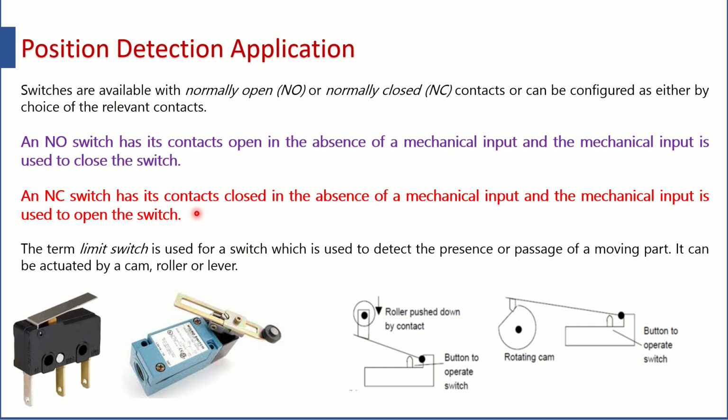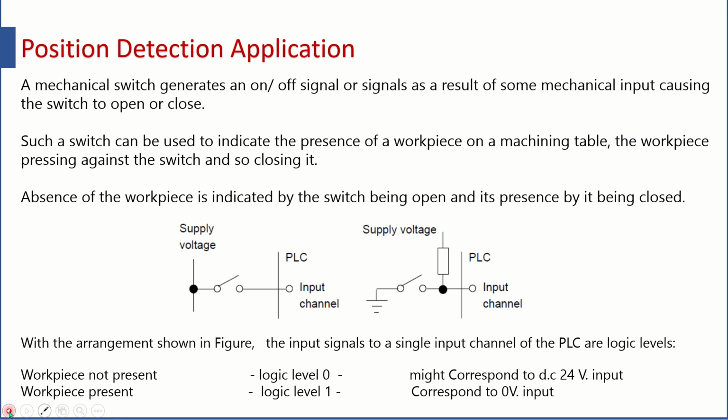If it is not aligned with the line, the switch will not be pushed. Very easily you can design such things. Such concepts are many times called Poka-yoke concepts in Toyota terminology.